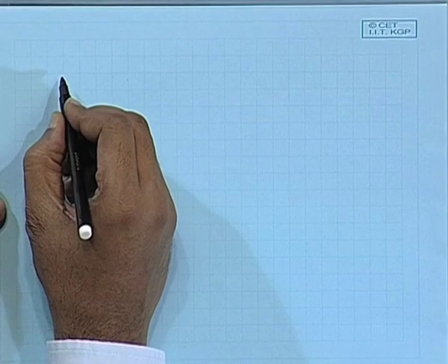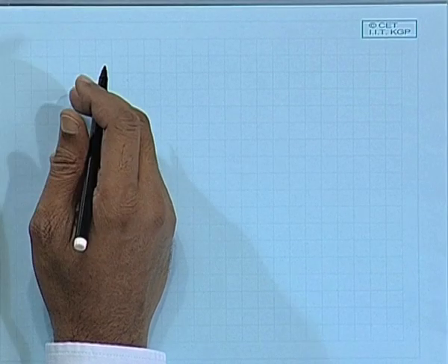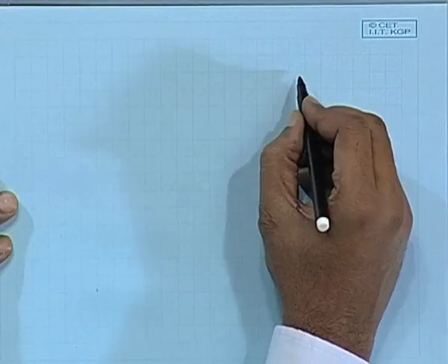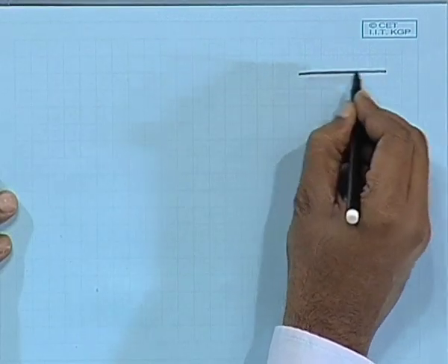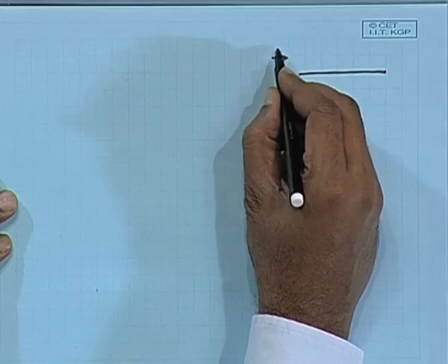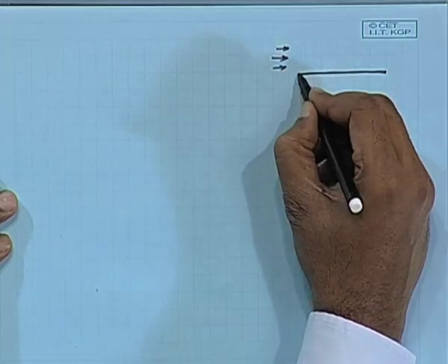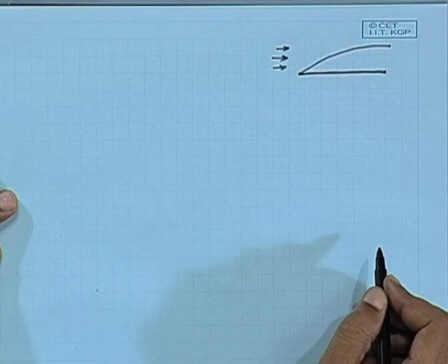So, I am going to write the Navier-Stokes equation for such a system and then simplify the terms and find out if we can have some sort of a governing equation with proper boundary conditions for boundary layer flow. So, I am writing the two-dimensional form of Navier-Stokes, zero pressure gradient, zero gravity flow. That means it is a case of a horizontal flat plate over which there is some flow resulting in the formation of a boundary layer.